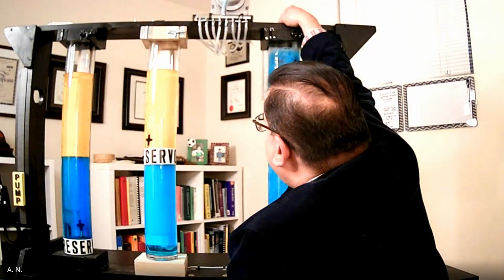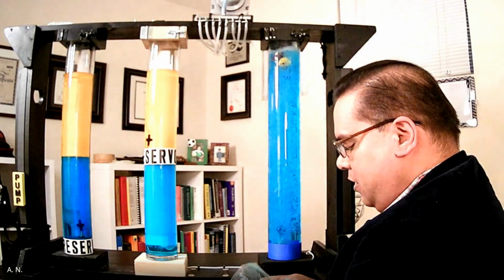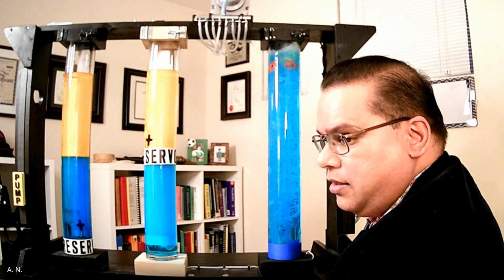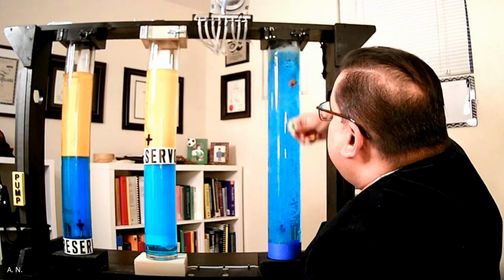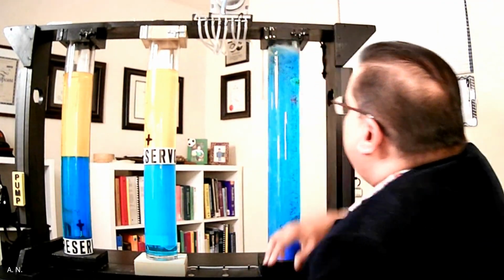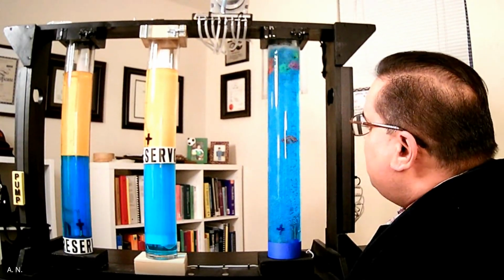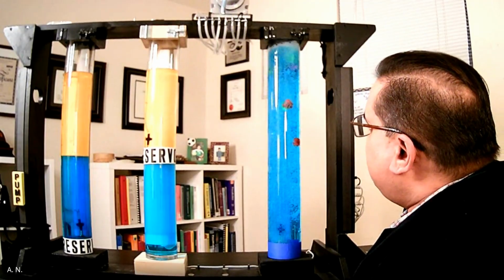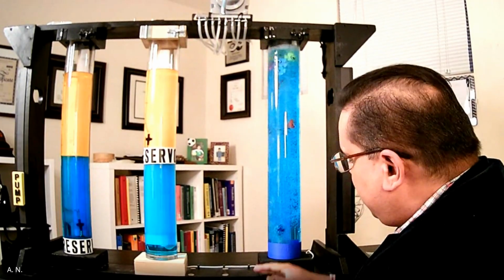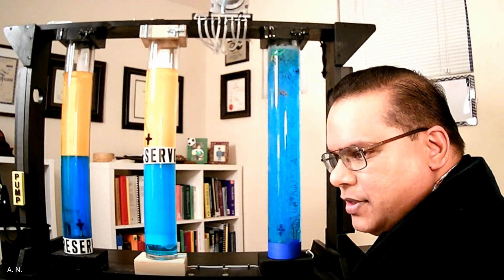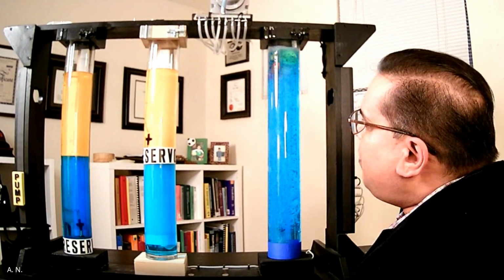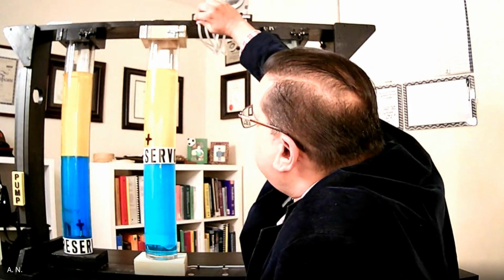So right now the current understanding is that if you put chemicals on the casing side, they won't actually reach down your pump, right? They'll just sit on the top. So these fishes are like your chemicals, yeah. Now right away we see, well, they're kind of going downwards, but not really reaching the pump. Let's pretend this is your pump, right? But what would happen if I increase the gas rate?